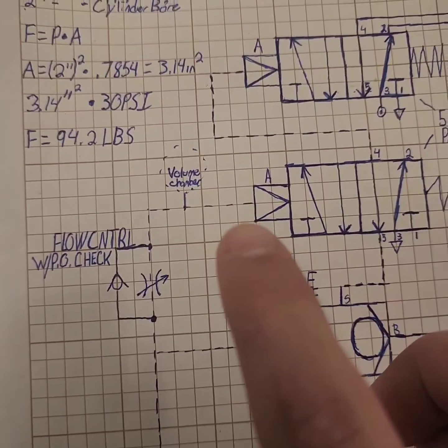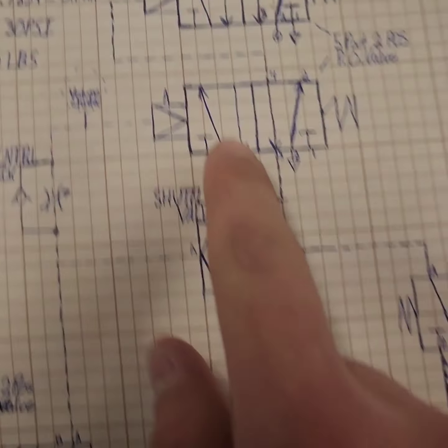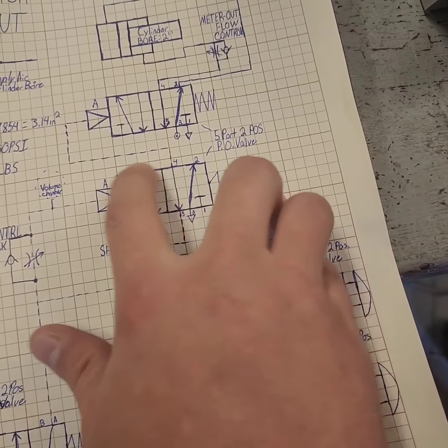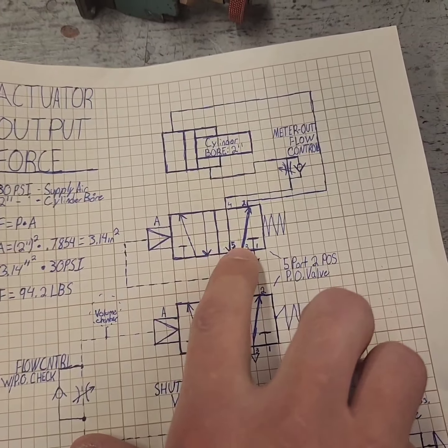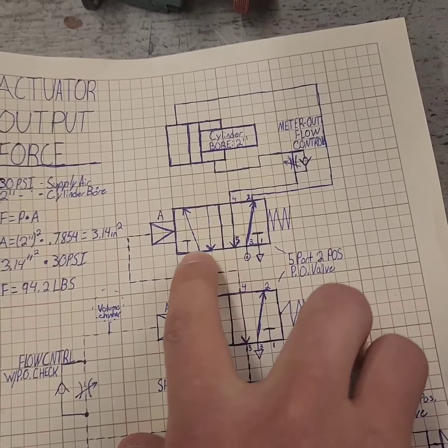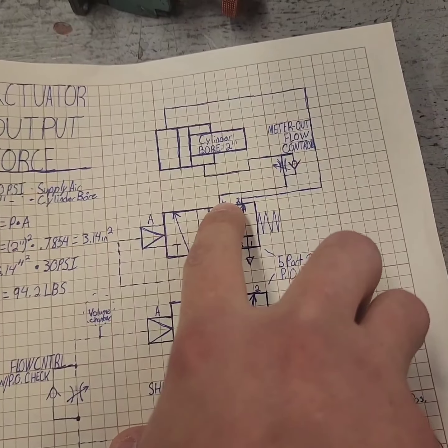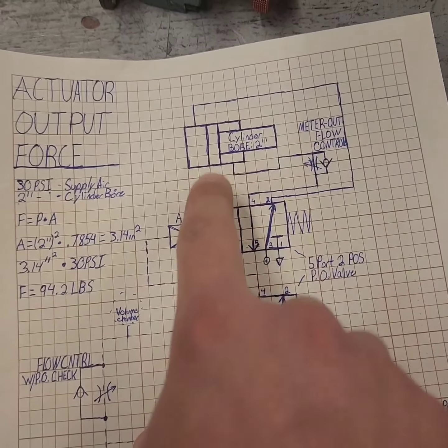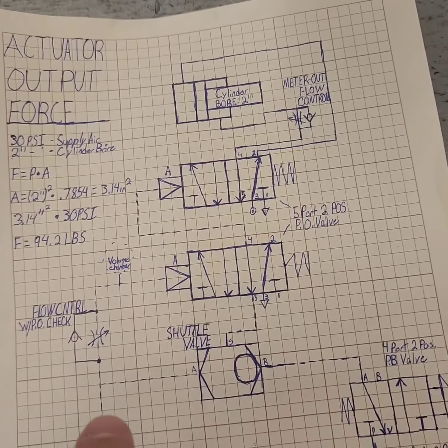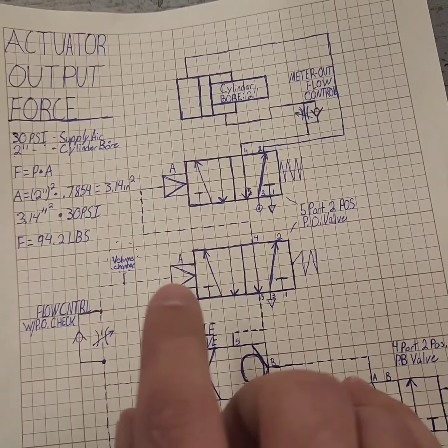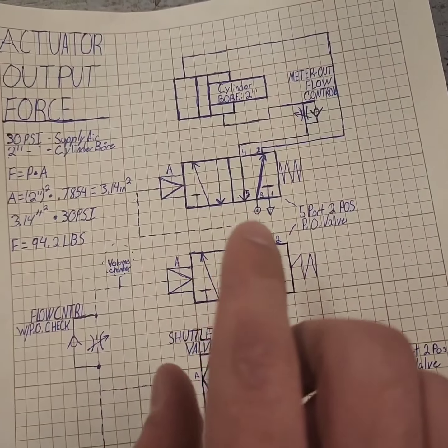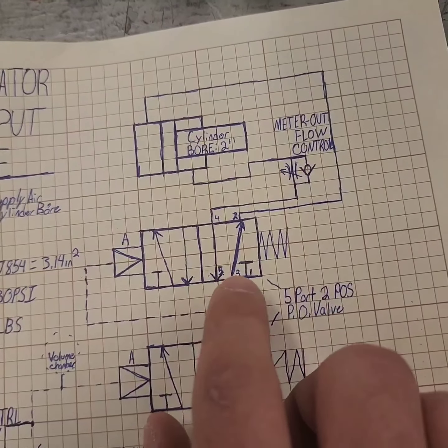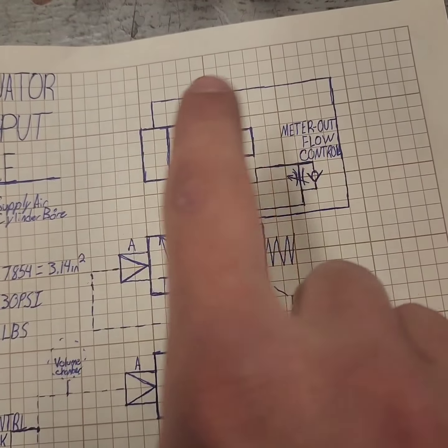So once the volume chamber is full, it'll actually pilot operate this valve right here. And what that's going to do is, because it's normally passing right now and pushing this second power valve over, the air is actually coming through right here to port 4, and that's going to come up, pass right past there, and that's going to make it retracted in a normal state. But then when you press the button, it's going to fill up the volume chamber, click that over, and it's going to push it back to the normal state, where then the pilot on the power valve is actually going to extend the cylinder.